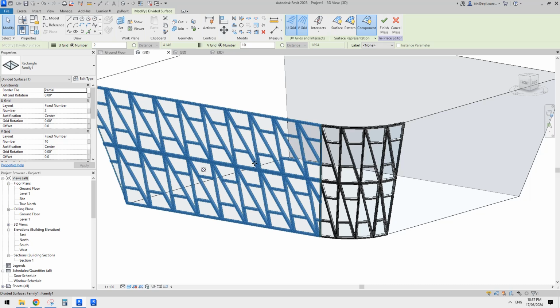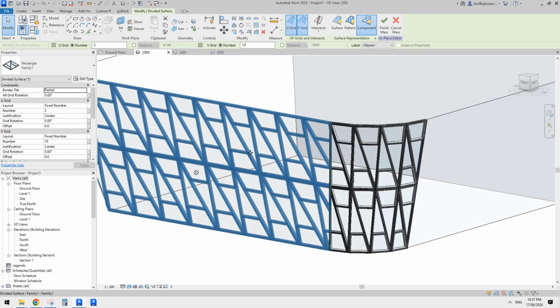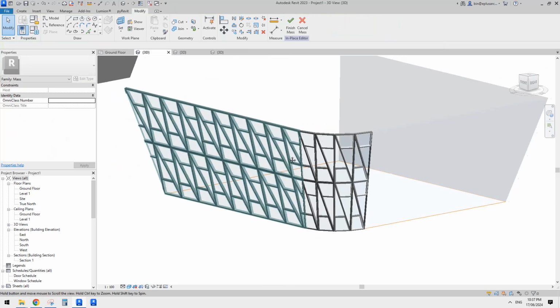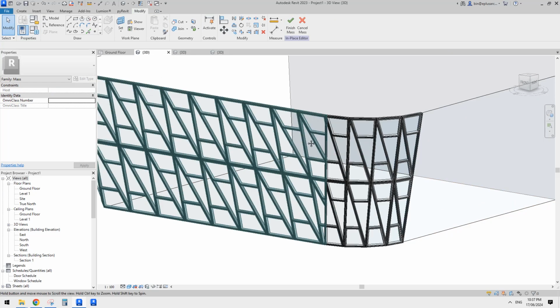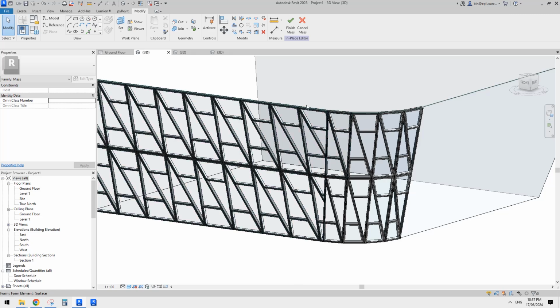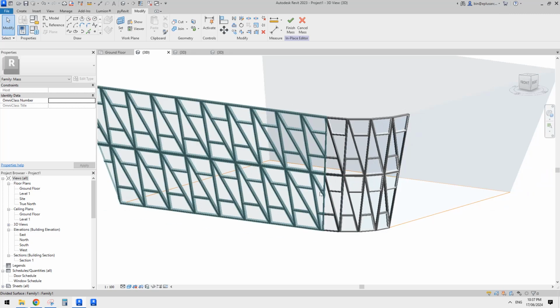So probably instead of having a 3-point adaptive family, you can directly create that pattern into the pattern-based family. So I'll leave that to you, but let's see if we can fix this bit.